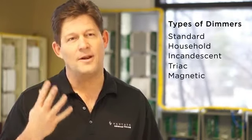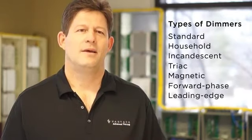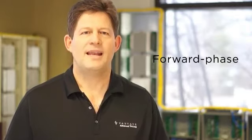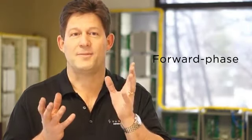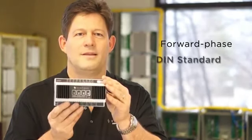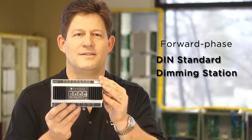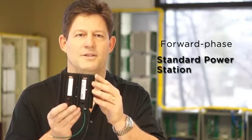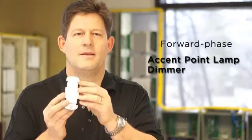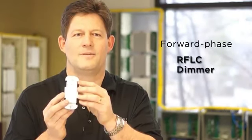A dimmer with the output characteristics demonstrated here is known by many names, including standard dimmer, household dimmer, incandescent dimmer, triac dimmer, magnetic dimmer, forward phase dimmer, leading edge dimmer. We'll refer to this throughout the remainder of the series as a forward phase dimmer. Vantage offers several varieties of forward phase dimmers, as seen now: the standard dimming module, the DIN standard dimming station, the standard power station, the scene point dimmer, the accent point lamp dimmer, the RFLC dimmer.